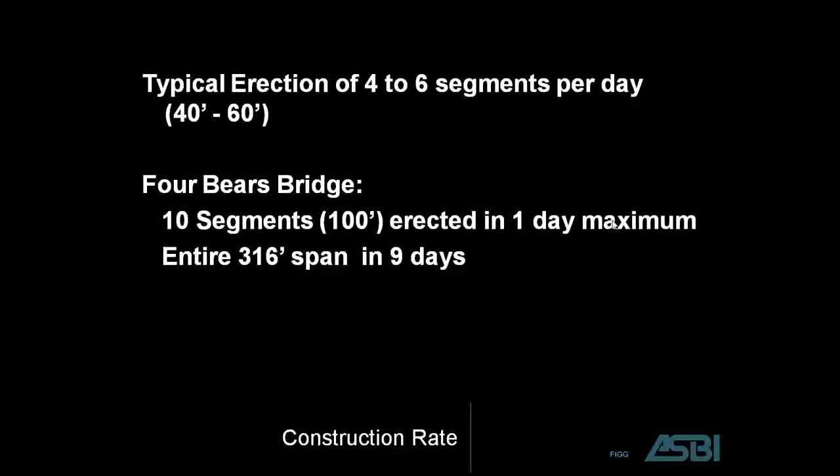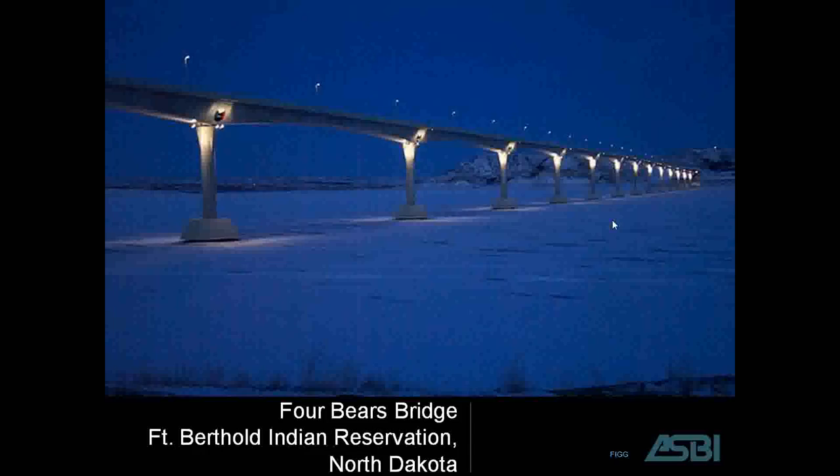In the typical erection of the bridge, there were 4 to 6 segments erected per day, and that's 40 to 60 feet of bridge. The maximum segment erection was 100 feet using 10 segments in one day. The entire 316-foot span could be erected in 9 days.